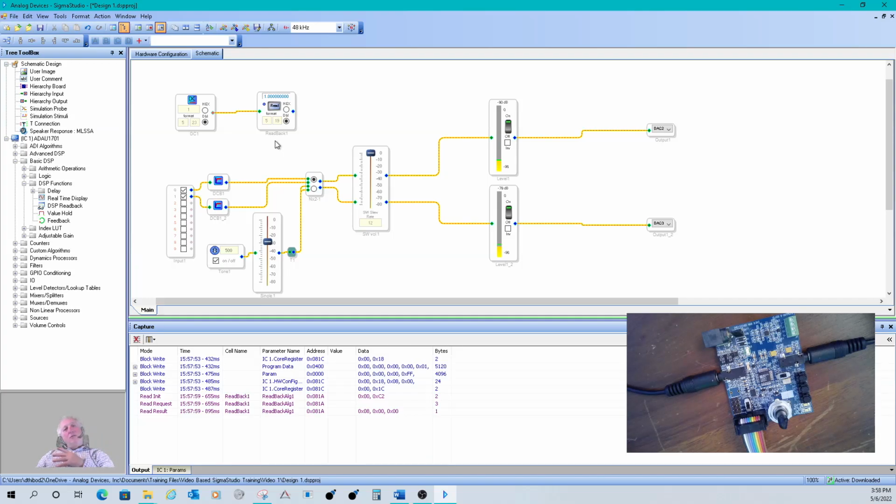In the later DSPs we fixed this, but in this early Sigma 100, the only way to do read back is with what's called a data capture cell, and it captures the accumulator at a certain point in the program counter and downloads that. That is a 24-bit read. The core is 28 bits. So there's 4 shy. So notice the DC cell says 5.23, but the readback says 5.19. That means the bottom 4 bits you do not see.